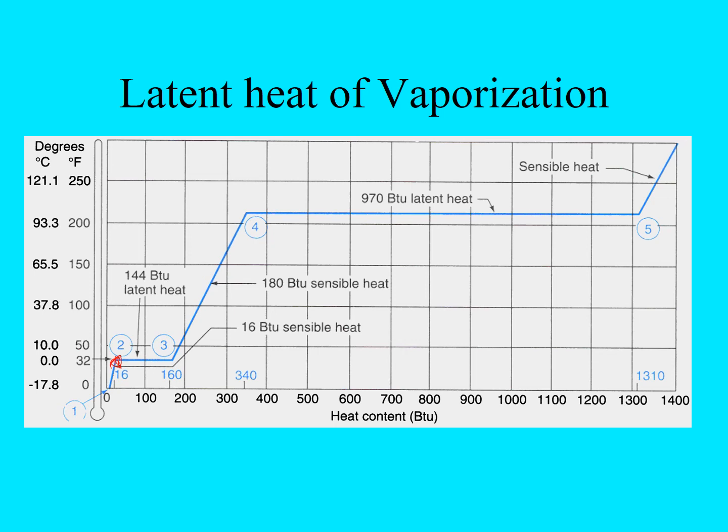And while we're adding heat to it, the ice is going to start to melt, okay? And once that pound of water has absorbed 144 BTUs of latent heat, in other words, there's not a temperature change taking place between point 2 and 3 on this graph. So until we get here, once we get 144 BTUs in there, now we have all liquid, okay?